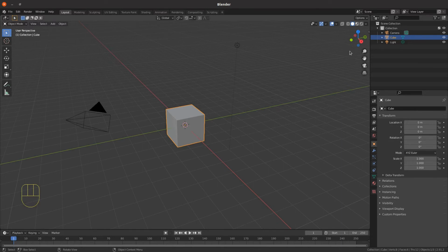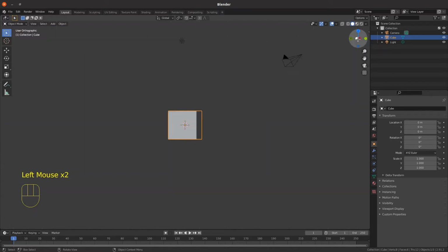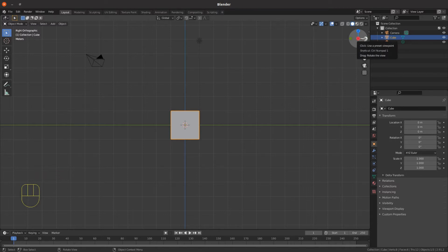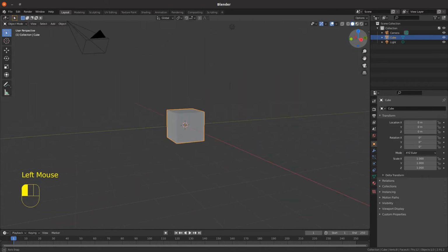So we'll quickly look at the navigation gizmos, and you've got the 3D axis, which gives you the set scenes. If you click on any of the end buttons, the red x-axis, you can click on it again and it goes round to the other side of the x-axis. If you want to look at the front view, click on the y-axis, or click again and you go to the back axis, and the same with the Z view. You can look at either the top or the bottom of the Z view by clicking on that, or clicking and dragging anywhere that isn't a hotspot but within the grey circled area allows you to pan the view to however you want to look at the view as a 3D view.